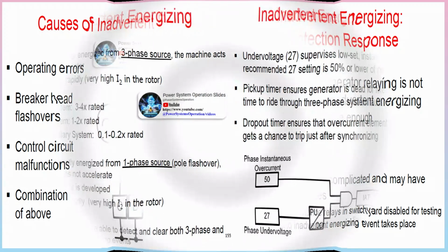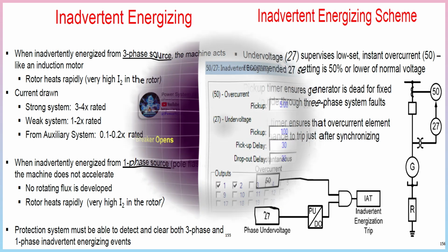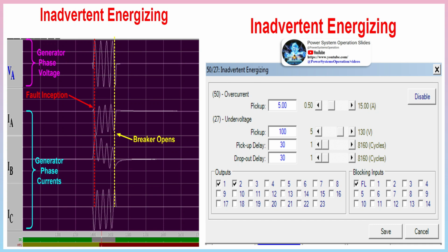In a steam turbine, the steam acts as a coolant, maintaining the turbine blades at a constant temperature. Failure of the supply will therefore result in overheating due to friction, with subsequent distortion of turbine blades. The failure of steam supply can cause severe mechanical damage in addition to imposing a heavy motoring load on the generator. A reverse power relay is used for this purpose. As soon as the generator starts rotating in motoring mode, the reverse power relay will trip the generator set.